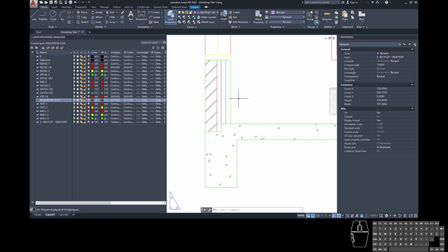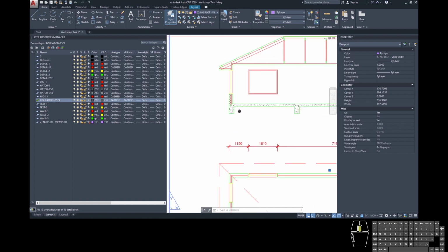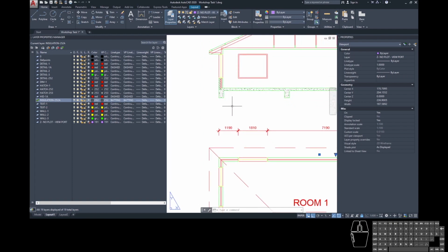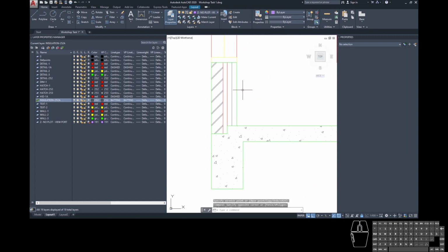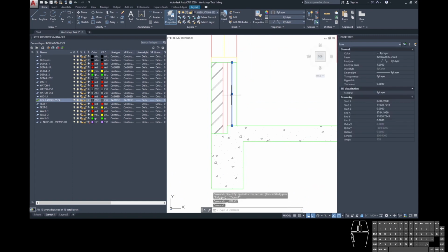But here you can't see the wiggly line at all. So what I don't want to do is change the global line type again. The global line type is what we use to change this dash, but I want that dash to stay the way that it is currently. So what we're going to do is, this is the exception to selecting and changing a property. This is the only time that you ever do this, is that you are fine to change line type scale here. So this is different to the global line type. This is specific to this object.